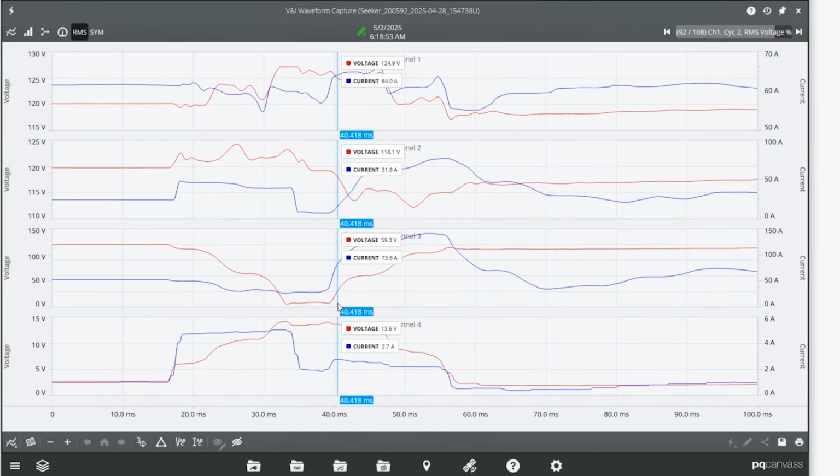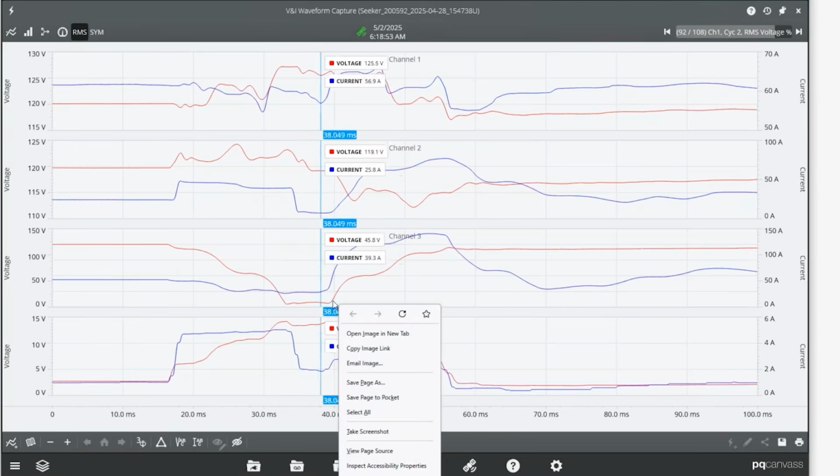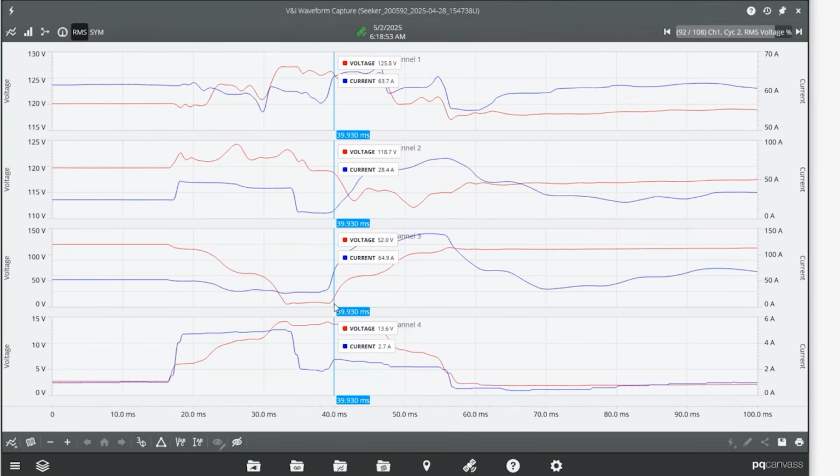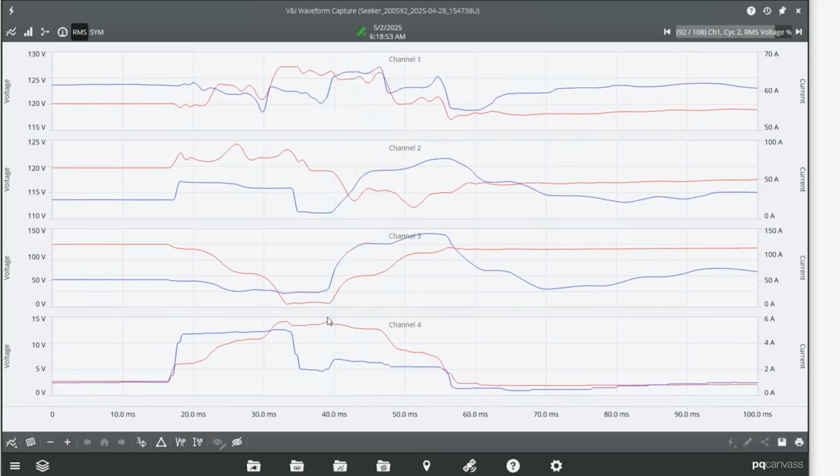In fact, you see an increase on one phase, the voltage swell on phase A when looking at line to neutral, because as the fault current flows on the single line to ground fault, the other two phases actually increase in voltage looking at line to neutral. But again, that's a much different picture than the equipment is seeing. So here we have both views available: the view from the utility standpoint of what they are delivering to the customer, and the view from the customer standpoint, what my three-phase equipment is actually seeing.